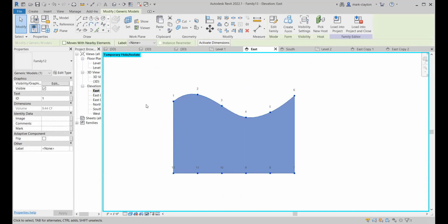I can load them into a project, and then I can put a tag on each of the views, so that now that number is on, that ID is on the view. And when I laser cut it, I can laser etch that number into the view. So then when I get them off the laser cutter, they're all nicely numbered. I can put them together and I'm just ready to go. I can glue them together and I can go on to my casting phase.